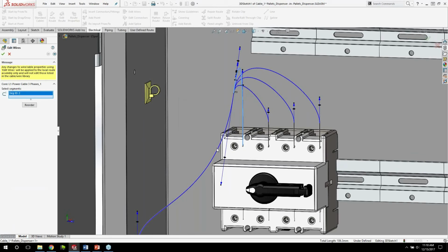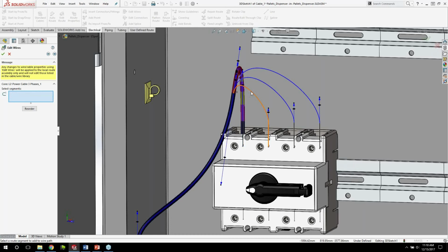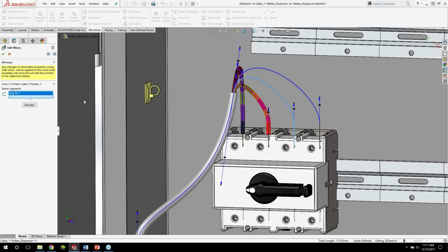this one here. Now it's letting me know that this doesn't meet the requirements for the selected bend radius for that specific wire or cable. So it's saying, do you want to route anyway? So we're going to go ahead and say yes. So it's pretty much doing that error checking there, letting you know, like, hey, this is going to be putting a crimp in your wire or cable. And as I go through and selecting this, you can see those wires get added, and this cable gets a little bit fatter, right, because it's taking into account all those ODs there.